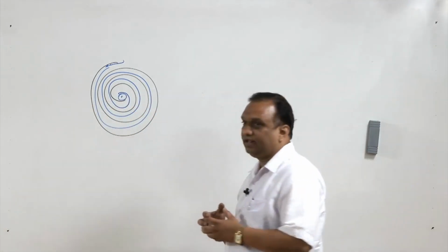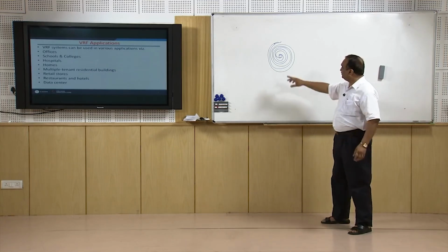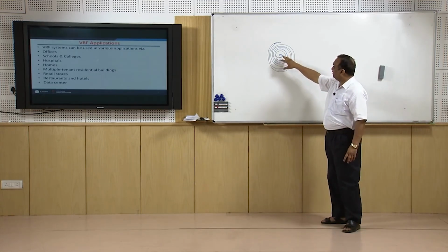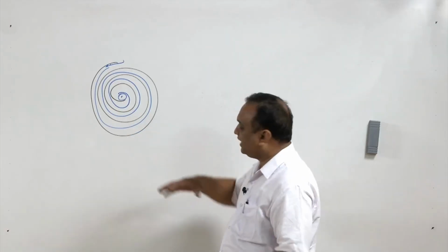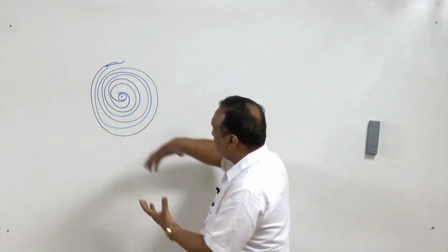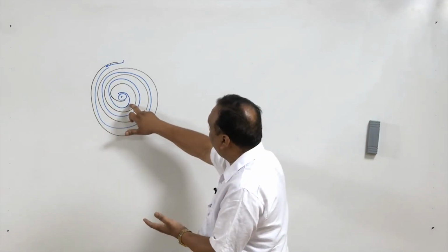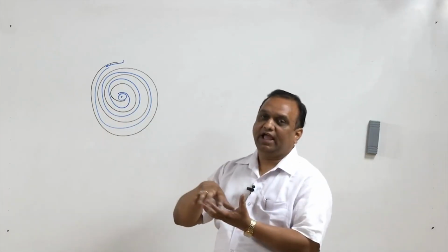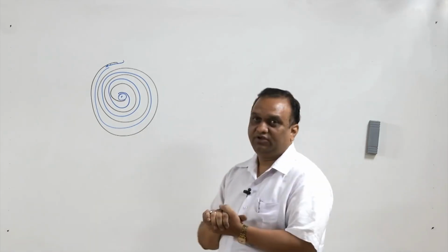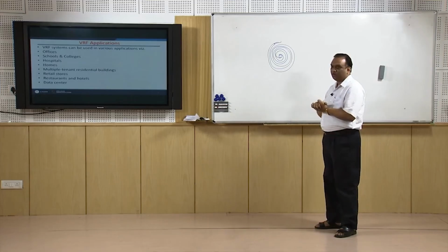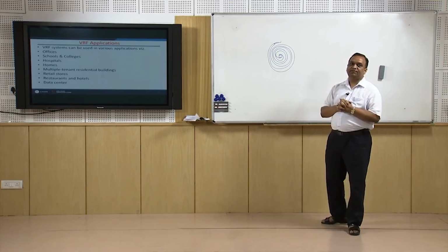Now in this compressor, suppose the black one is a fixed spiral and this is the spiral which revolves around the fixed spiral. If I control the frequency of this moving spiral, I can control the mass flow rate also. This type of technology is known as inverter technology, where with the help of the frequency of the moving spiral the refrigerant flow is controlled.